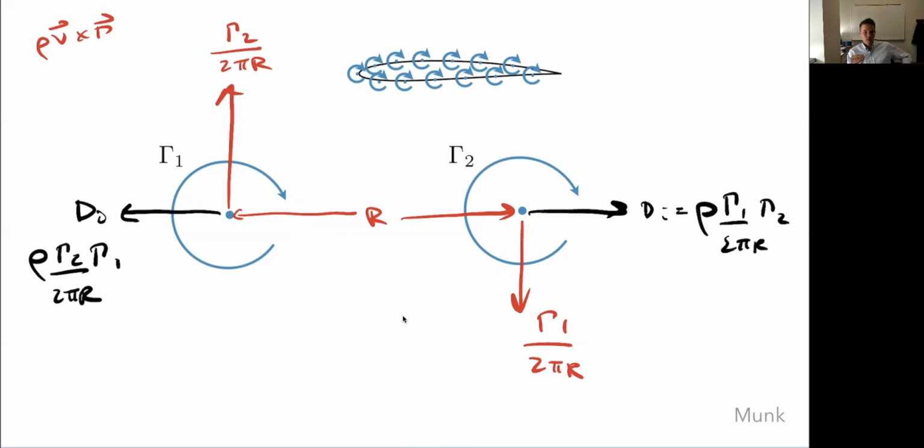And even though we did that Kutta-Joukowski thing, where we drew an airfoil, and we said, oh, it's just like V infinity, and then we could calculate the downwash. And from that downwash, we could use Kutta-Joukowski and get lift and drag. Well, we just showed that downwash is not actually correct. The magnitude is different. It's not CL over pi aspect ratio, it's modified.